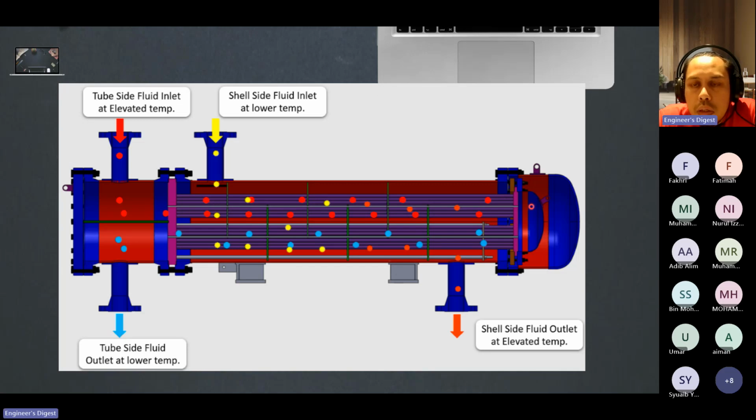thermal expansion. If we have a high thermal expansion, this floating side will go to the right slightly, exaggerating, but it will go to the right, and then it will contract back again. So any thermal issue, the floating side will be able to handle. And it also caters for an issue from the fixed heat exchanger.